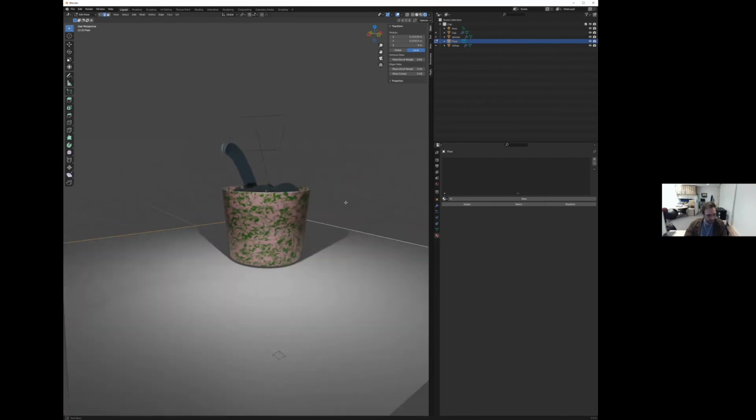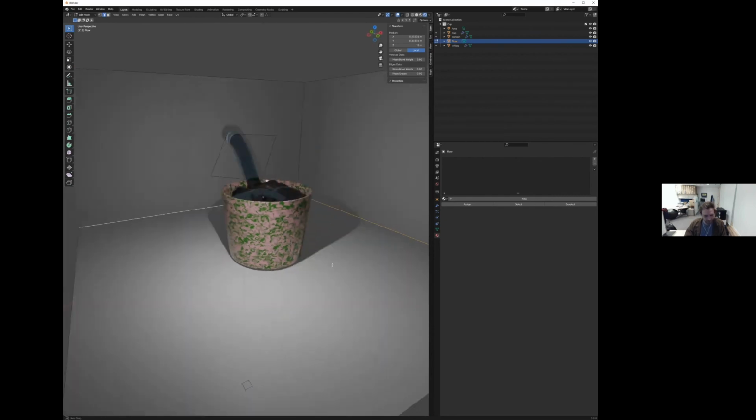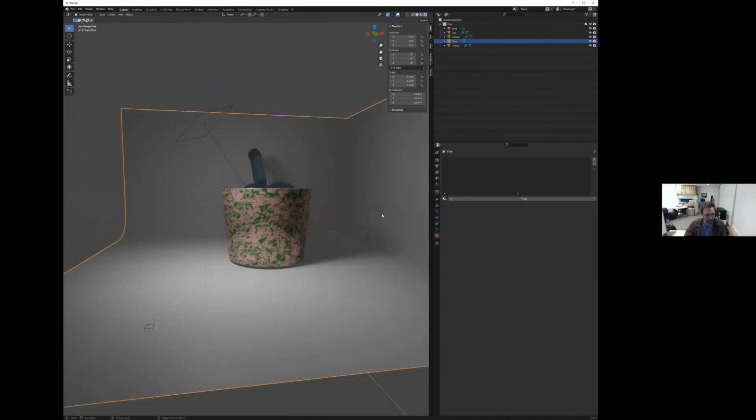As I grab these, I extrude this up in the Z direction. And then I take these two, and this is one of the last hotkeys I'll show today, Control B for bevel. Then I increase that, and I roll with my wheel. This will smooth out that edge. So now if I click it and do smooth, now I have a smooth background.